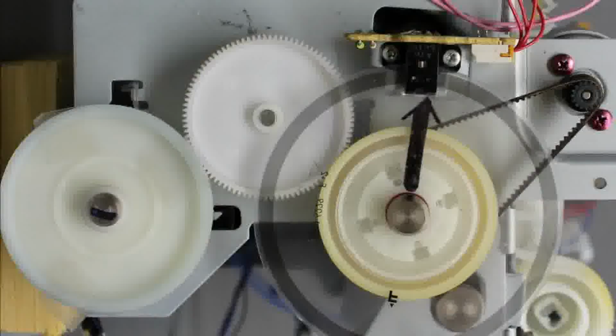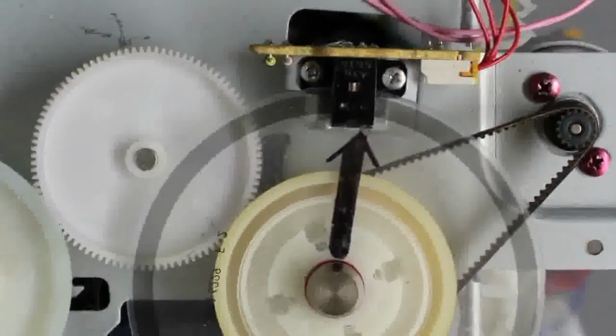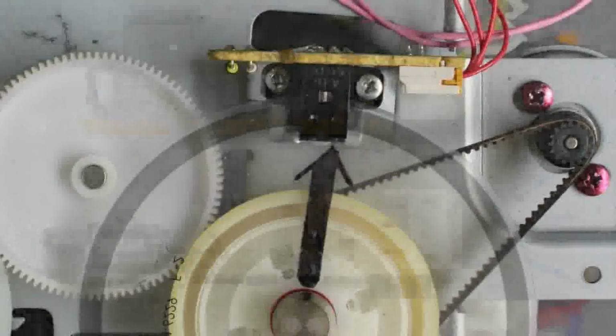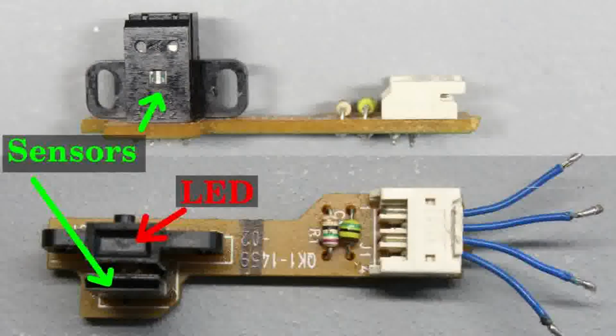Printers and scanners usually use rotary encoders having two receivers in one housing, thus they are very likely sources of that type of sensors. The receiver side can be easily distinguished from the LED side since only one LED is used to illuminate both receivers, thus the two pins are running to the light emitting diode.